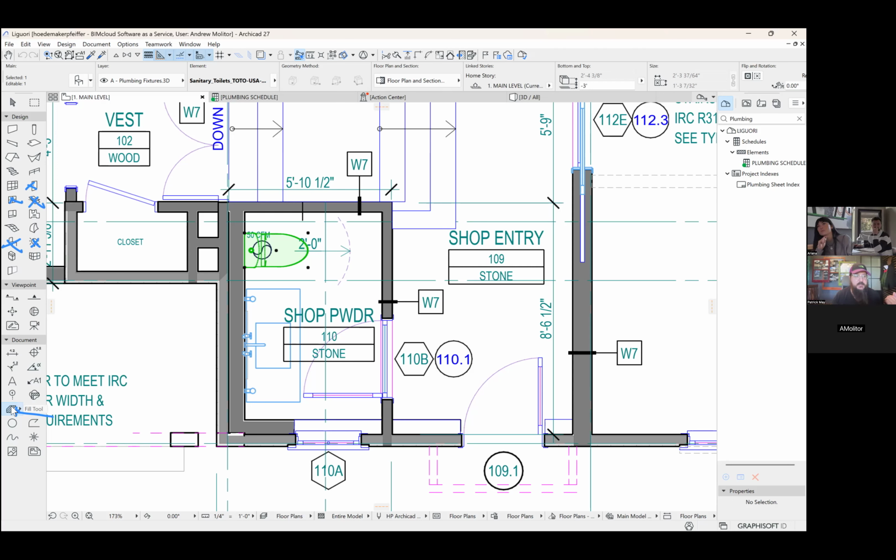If you need it to be 3D, use this top grouping of stuff. Beams and columns, slabs, walls, all of that works great. The morph tool works great. The shell tool works great for modeling 3D geometries. If you just need it to be a 2D symbol, like maybe you wanted to show the P trap here under the sink, whatever that design needs to be, just go ahead and drop a fill in here.